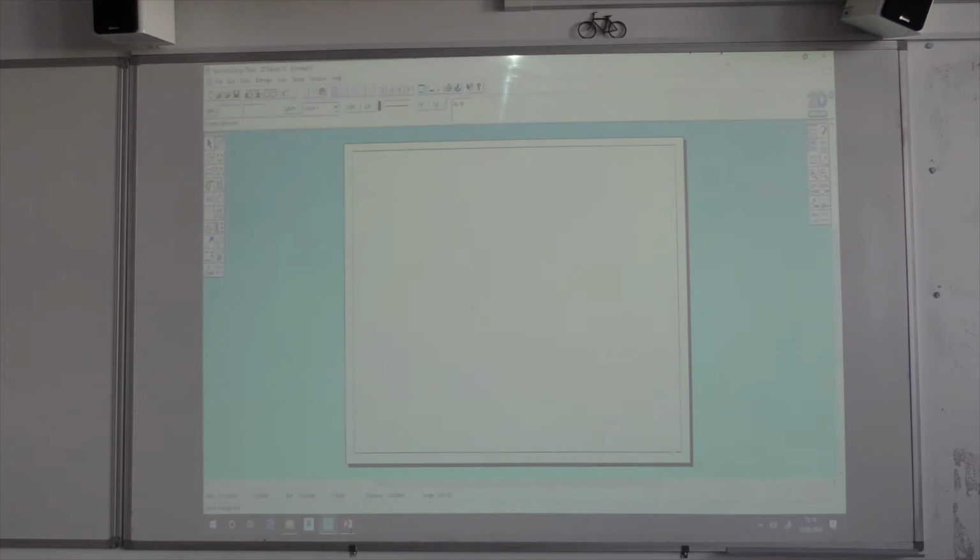I've got a basic border, but it does not contain the technical information that we would need on each drawing page. So I'm going to measure out 60mm from the side. I've stayed on line, and I'm using the distance feature down along the bottom, and the distance tells me that this is 60mm. If you can't see where I mean, it is down here. I'm looking at this number and I want it to be 60. Currently it's at 50, it's at 60.